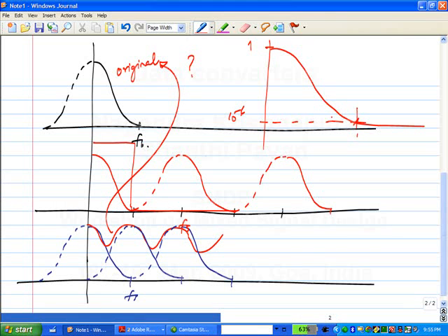Now, what does this negligible really mean? One way to figure it out empirically. Let's say you don't do any theory because it's a little bit hard to do. So you first put a filter to this part and then play it back and see. If it sounds the same, then you say that is okay, right? That is one way to look at it. So you decide something is negligible. So for instance, for human audio, it's been decided that obviously maybe we may be emitting some sounds beyond 20 kilohertz also, but if we take from 0 to 24 kilohertz, that's it. We don't need anything more, okay? Because our ears don't respond to it, and we can't produce those sounds either. So that's what has been decided. Okay. Although if you take a finite segment of my speech, it is strictly not band limited at all, right? So there are some practical definitions like that.